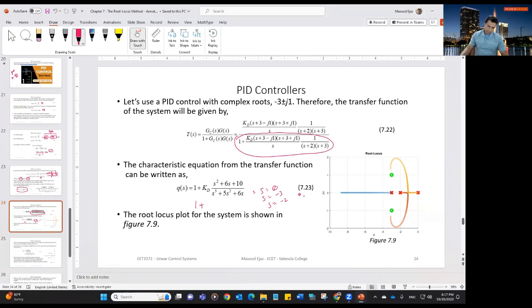to head towards the zero sitting on the negative real axis. And from these poles, as you can see with different colors, they start moving towards each other when you change the value of KD. Then the locus of roots are going to start moving towards each other. And at the breakaway point, they're going to break away from the real axis, and the set of poles coming from S equal to 0 is going to go to this zero, and the set of poles coming from S equal to -2 is going to move towards this zero, which is over here.